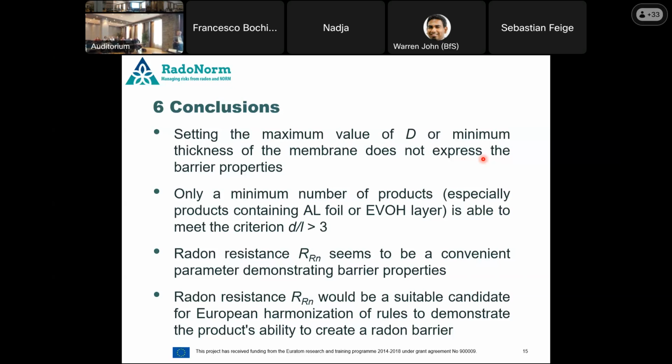Yes, I know that the classification of building sites into categories of radon risk may differ. Some countries use the indoor radon data, some geological data. For example, in our country, we measure directly the soil gas radon concentration on the building site and so on. But in fact, it's not so important which data you use, whether indoor data or soil data. The fact is that even the indoor radon data express the radon concentration in the soil.